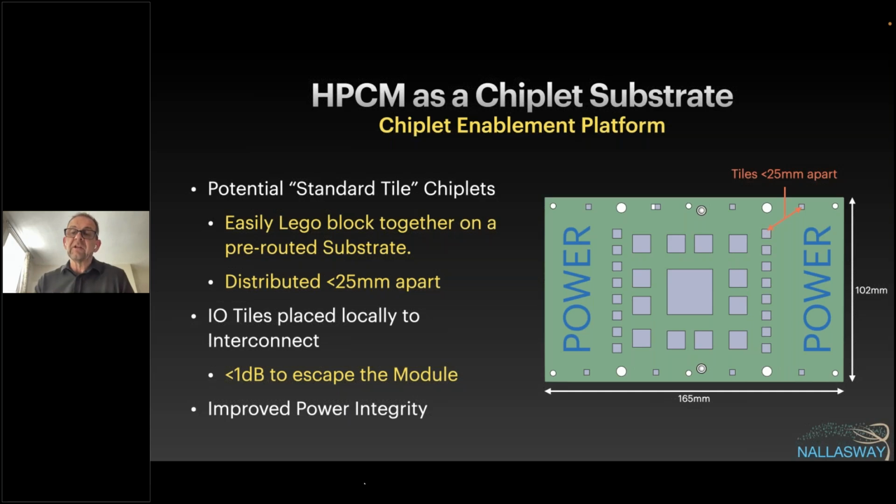EDSFF modules, the E3.S have a budget of 25 watts, I believe. Now we potentially could call more than that, but if you assume 25 watts times 16, I believe it comes out to about 1.4 kilowatts for the module itself, so 1 kilowatt for the powerful processor and 400 watts for the media devices.